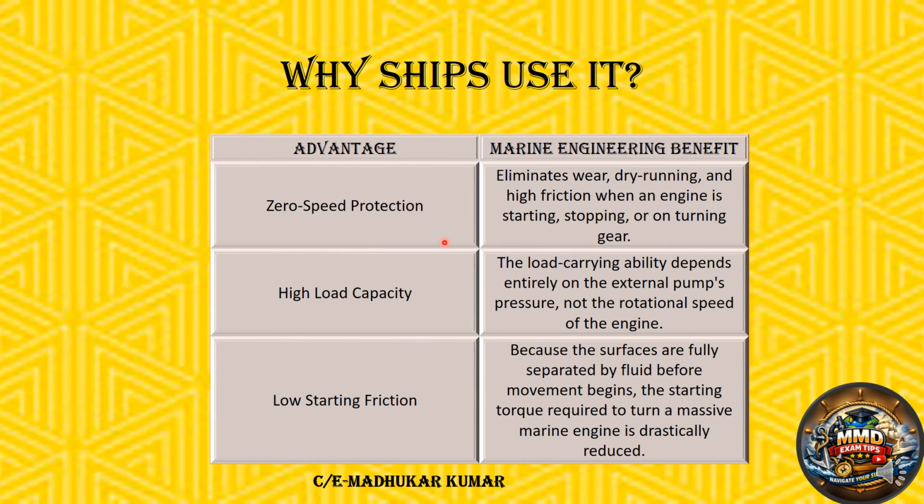Okay, why do ships use it? Why are we utilizing this? What is the benefit? What are the advantages? Zero speed protection. It eliminates wear, dry running, and high friction when the engine is starting, stopping, or on the turning gear.